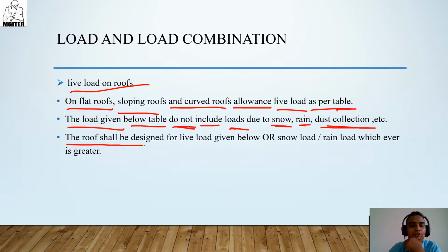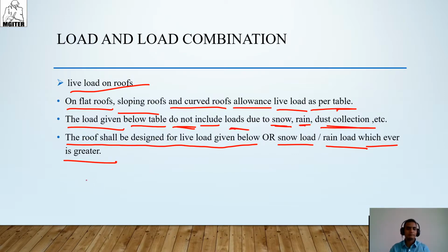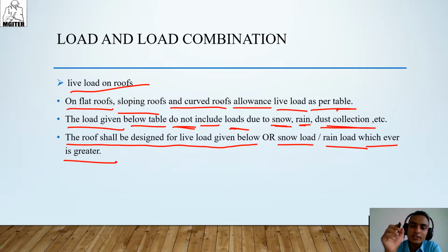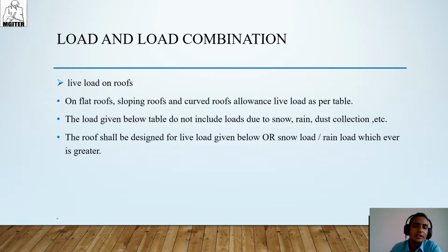Then the roof shall be designed for the live load given below or snow load, rain load, whichever is greater. Okay, meaning the load given in this table is only live load, and snow load and rain load are not included in this table.